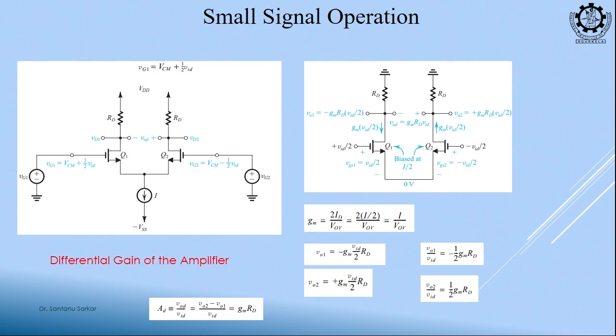So, now this is your circuit, and if I want to do the small signal analysis, okay, DC wise we have seen that DC gain is 0, VD1 is equal to VD2. So, subtraction is 0. Now, we have to see the AC wise. AC wise what should be our gain, that we have to calculate. Now, while doing the AC signal analysis, if there is a DC voltage source we should short it, if there is a current source we should open it, remove it. So, if we remove it, you see this.